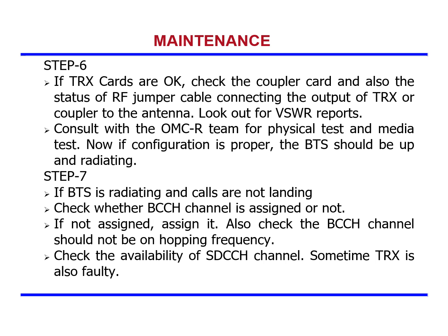Step 7. If the BTS is radiating and calls are not landing, check whether the BCCH channel is assigned or not. If not assigned, assign it. Also check the BCCH channel should not be on hopping frequency. Check the availability of the SDCCH channel. Here SDCCH stands for Standalone Dedicated Control Channel.